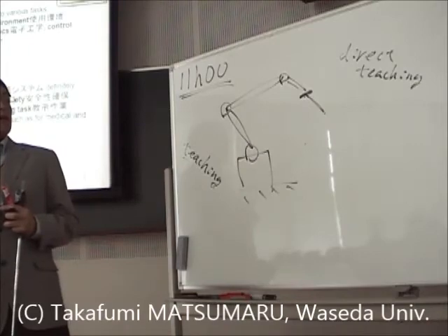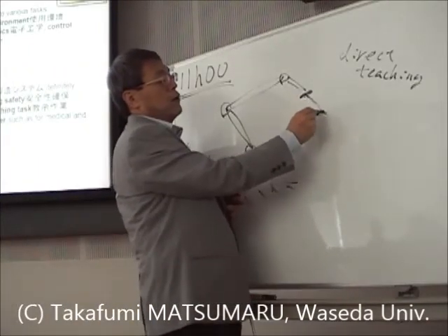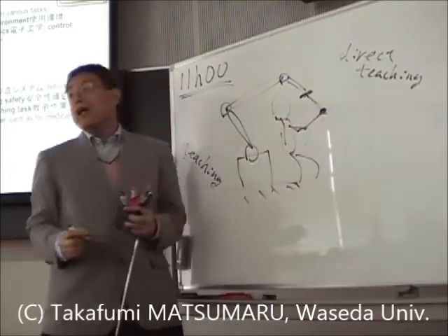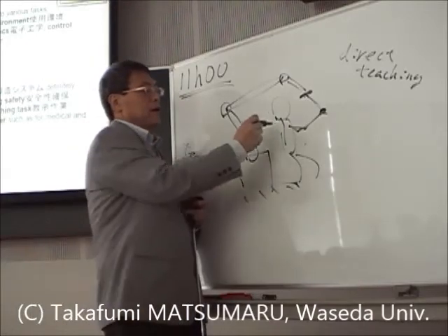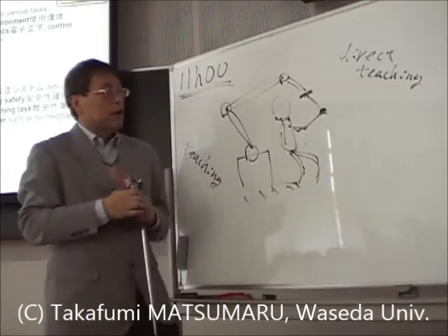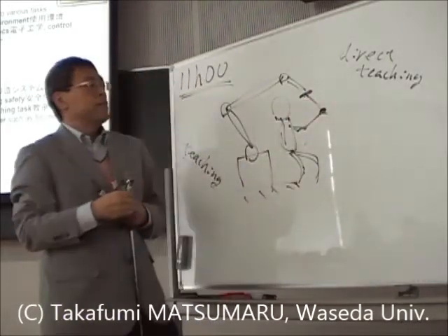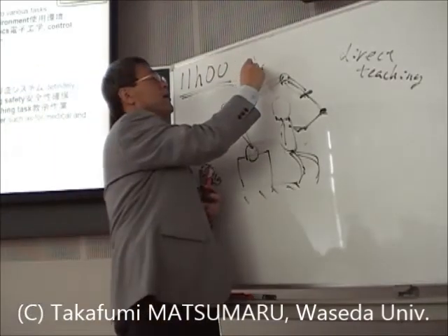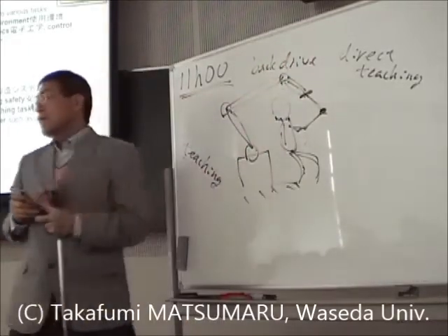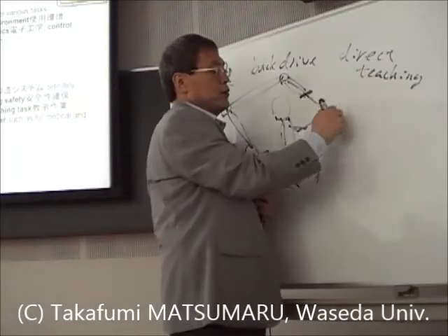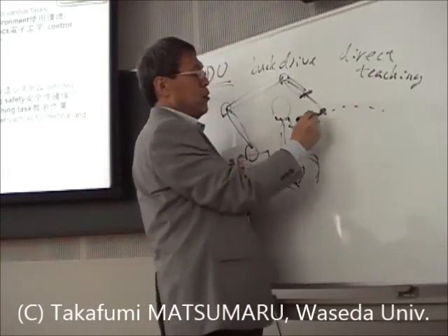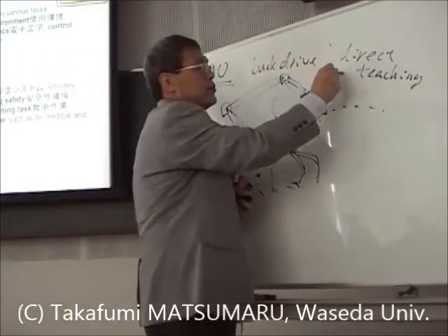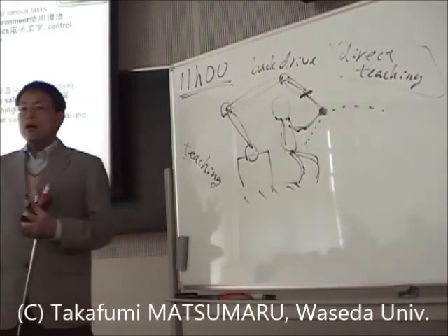Move the robot directly and the robot remembers the movement, the trajectory. Here, the human worker holds this end tip directly and operates this path trajectory by back driving this robot. It is called the back driving method: directly move the end tip and present this trajectory by operating this end tip's position and orientation. This is one method, called the direct teaching method. What is another way,